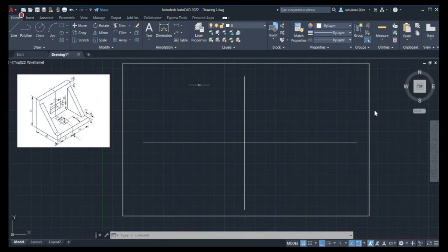So you have to draw the front view here so that you can draw the left side view in the right profile plane. You have to decide before drawing the front view whether you are going to draw the left side view or the right side view. And how do we decide that? Based on the alignment of the object or the problem given to you. Clear? Yes, sir.